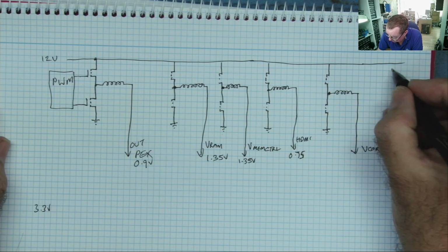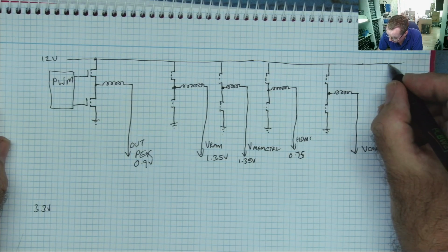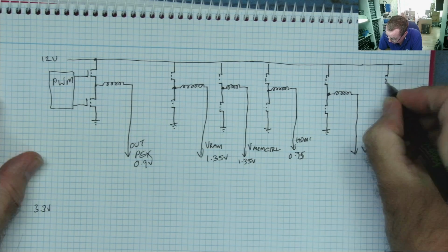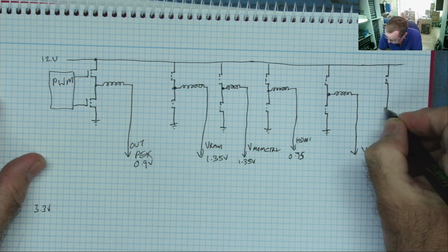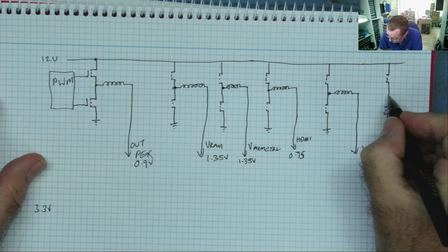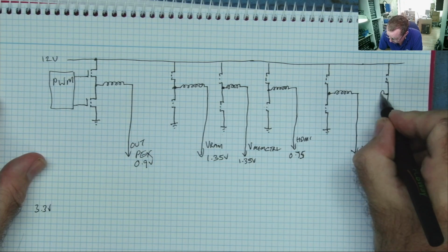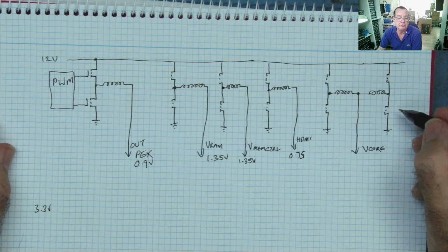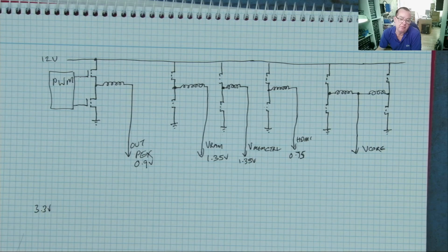So in parallel, what it actually means is you'll have another pair of MOSFETs, okay, to ground, and I'll draw the coil coming this way this time, it doesn't matter. And that's also driving there, so we've got 1, 2 phases, and we may have more than that, okay.